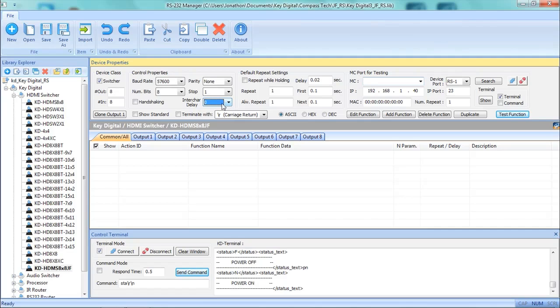Okay. Let's go ahead here and automatically apply the carriage return and line feed termination, since we have an opportunity to do that, and it could save us a few keystrokes with each command. We're not going to apply any repeats here. We are already connected to our MC2500 here, and we'll be testing out of port number 1.